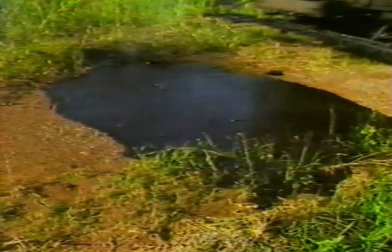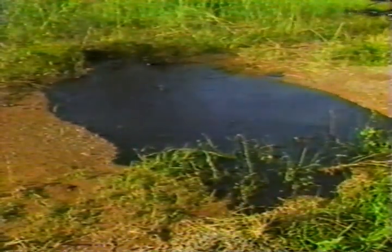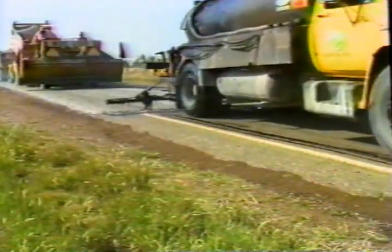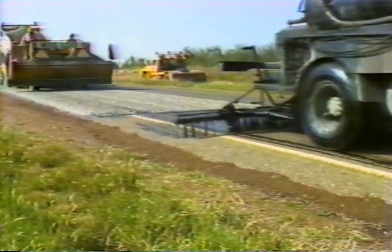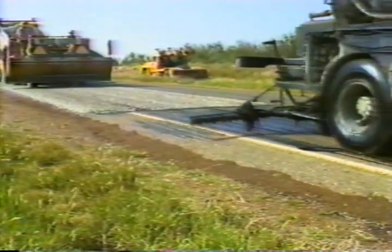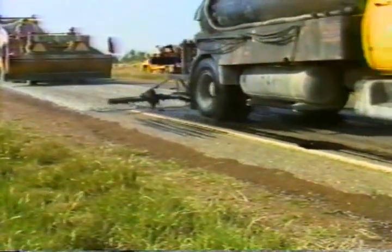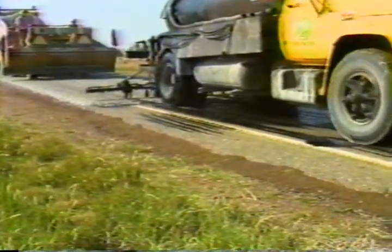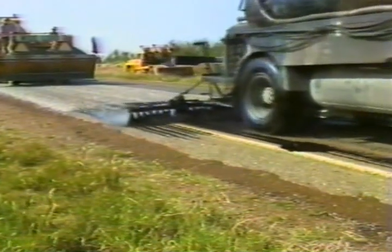If a distributor in this condition is used on the job, several problems will occur with the binder. First, when a clogged spray bar applies binder under normal pressure, the oil flow will be insufficient and the fan profile will be poor. If, on the other hand, the pressure is increased beyond the recommended 206 kilopascals to compensate for the restricted flow, the high pressure can cause emulsion oil to break upon impact with the road surface, separating the water from the asphalt and ruining the qualities of the binder.